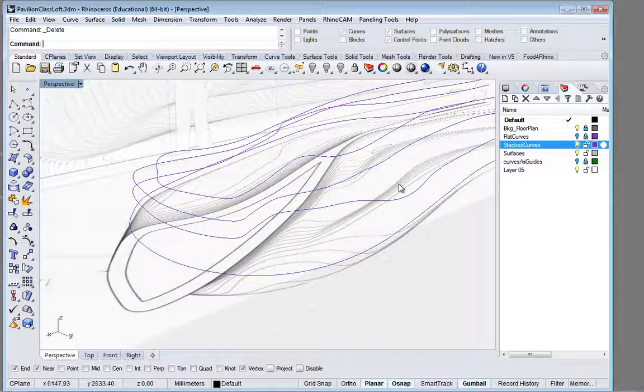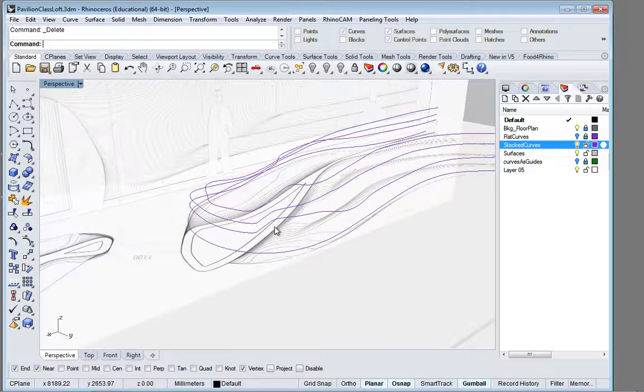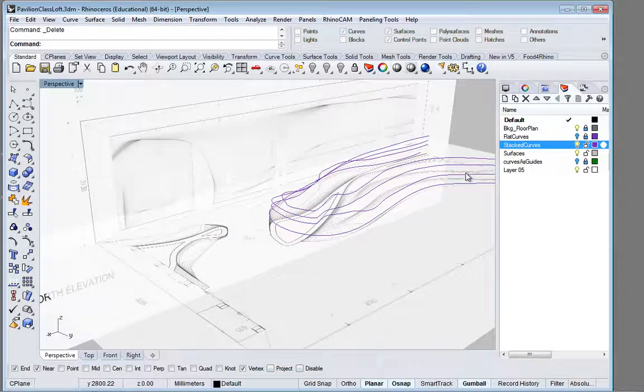Like if I had this surface down here flat and I had two of them stacked right next to each other, and then I had one above it and further away, it would create this weird kind of curve between the two of them, and you would get this crease in here. So you have to build it and then modify the geometry a little bit, build it. That's where record history comes in to develop it.